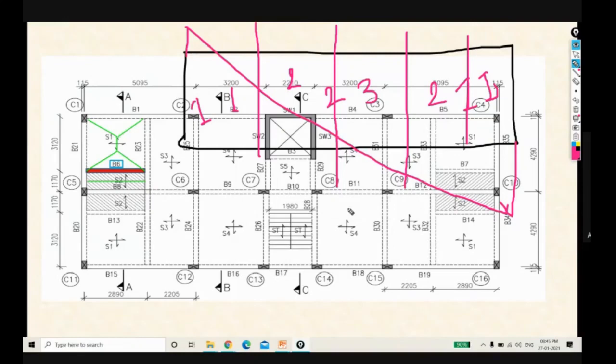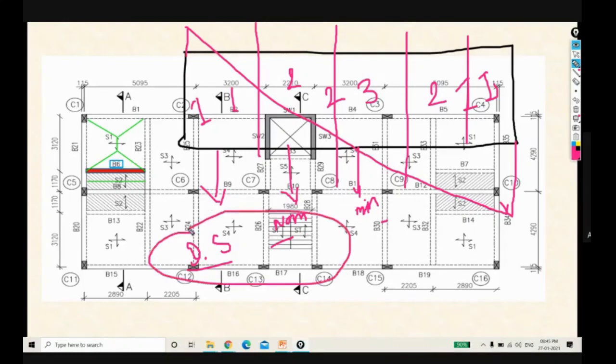Okay, so see, if we consider the three zones, basically this last zone has the maximum shear force, so here we are considering the design shear force. At this position we are considering the nominal shear reinforcement, and at this we are considering the minimum reinforcement. So design, nominal, and minimum, if you consider three zones for the shear reinforcement. And if you consider only two, in that case we are considering design and nominal. We are not going for the minimum. So such criteria is there.